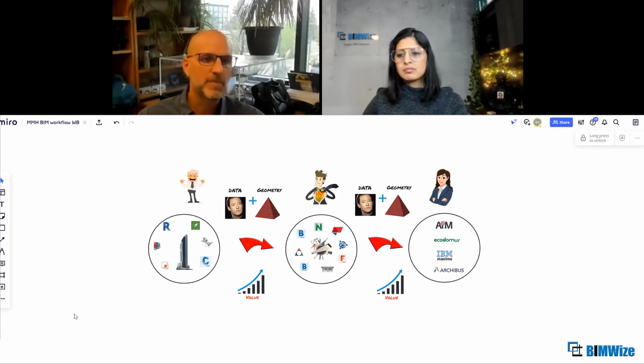So when you turn that into BIM, and I should specify, my biggest challenge with LOD is within the electrical and mechanical scopes, so I'll use a lot of those examples. When you have to go to the market and low bid, and the mechanical consultant is modeling everything to a certain point to get what we need to turn it into documents that we get a price for, they have to model to 95% or whatever you decide complete is, which is typically LOD 300.